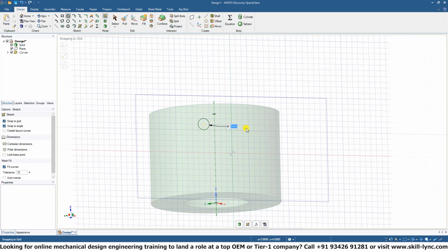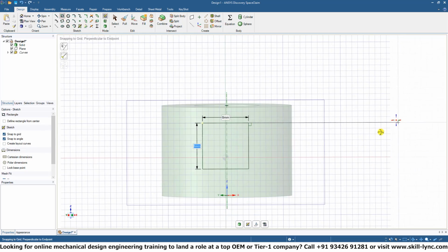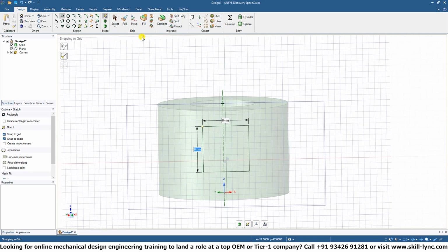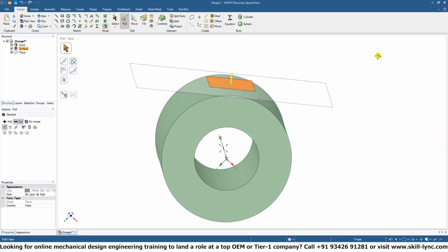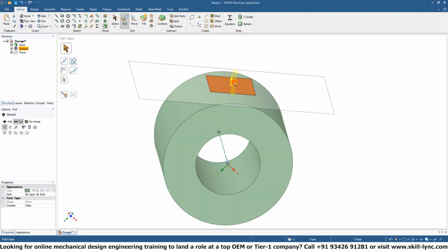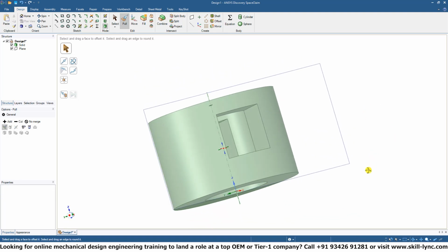So after we selected this sketch plane over here, we can start doing our little sketches. So we can do a few just as an example. Actually, you know what? Let's do a rectangular face over here, just like this, just so we can play around with a bit of a different geometry. If we go into the pull tool, click cut, select this new face or window that we've drawn, we can actually cut it straight through our model.